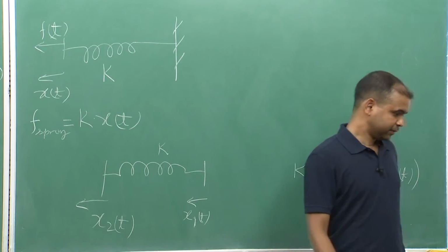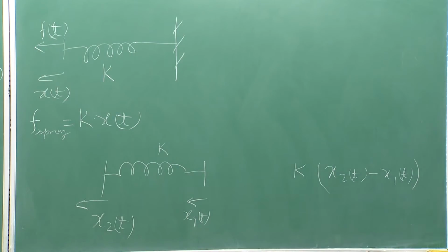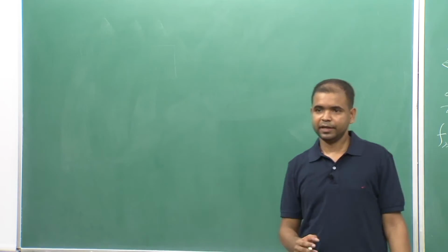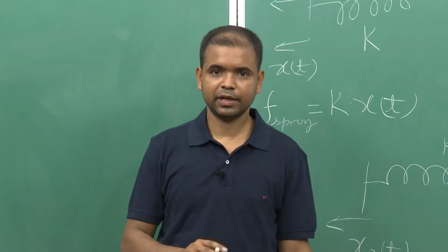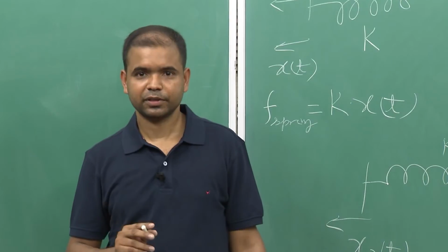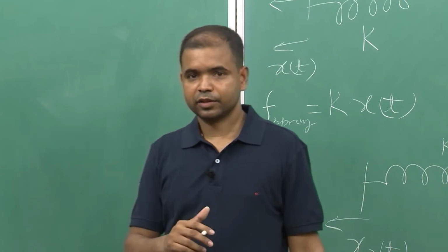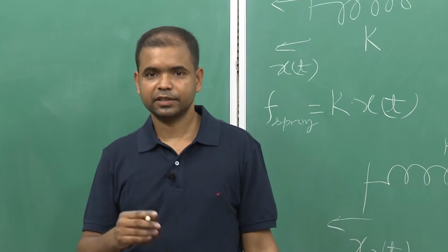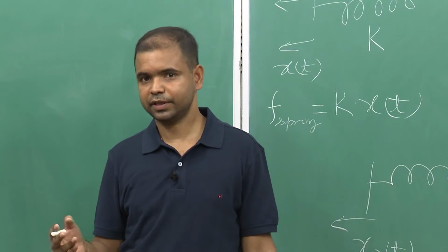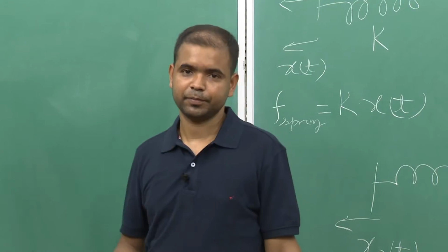The spring is also conservative in its nature, and it stores the potential energy of the system. So, the spring and mass are transferring energy to each other with a phase difference of 90 degrees, but the energy is conserved throughout the process. So, if there is a spring mass system and you deflect it, it will continue oscillating because there is no energy dissipating element.